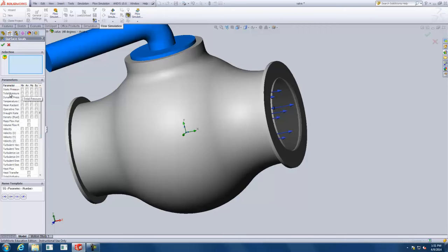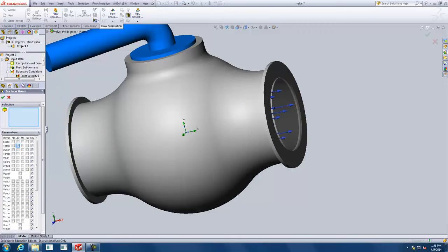It's kind of hidden there, but we're looking at the total pressure, and we'll take the total average pressure. So we've got minimum, average, maximum, and that's bulk. All right, so we're just going to go with the average total pressure. And again, the faces we want are the inlet and the outlet. We can right-click and select Other and try to do that again, but we've already done that, and we can use our previous definitions for the inlet velocity and the static pressure to do that.